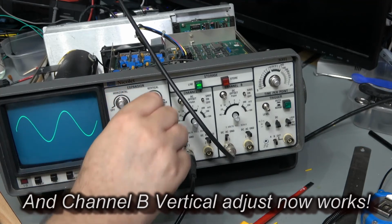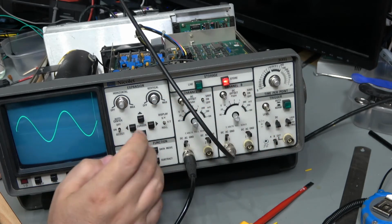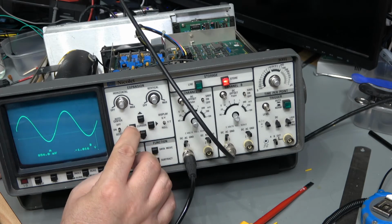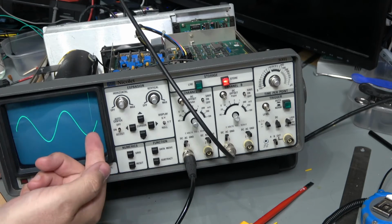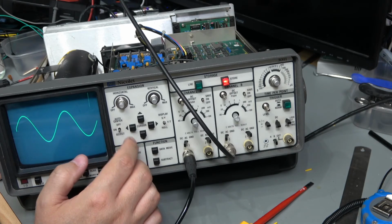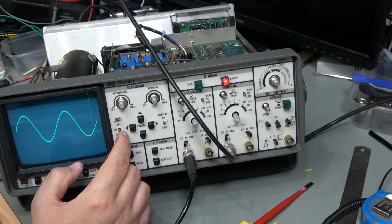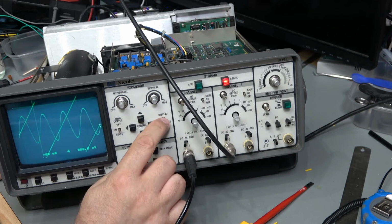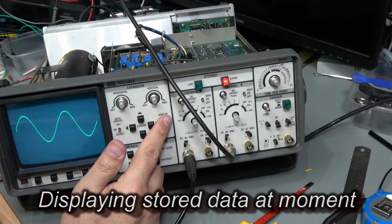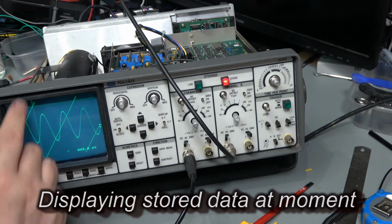Yeah, we can expand. Expand vertically. Cool. We can put it in memory. Yeah, and move cursors around on it. It's probably very difficult for you to see that on the screen. There's a vertical cursor and there's a horizontal cursor marking out the, so I can move the horizontal cursor basically. This button here enables me to choose horizontal cursor tracks the vertical cursor. Roll is just giving us a constant rolling signal. That is normal Y versus time.